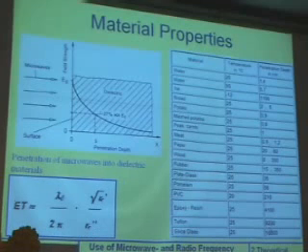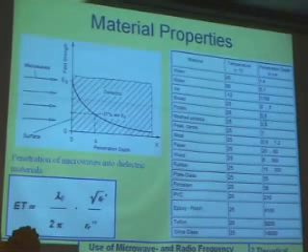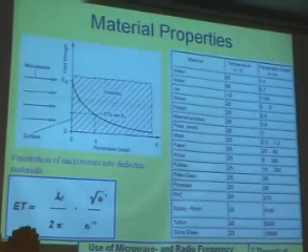If we change to, for example, Teflon, which is a very proven material to use in a microwave oven because it does not absorb microwave energy, Teflon has very low epsilon R, and therefore we have a high penetration depth. And if you look in agricultural material, for example, bread, you have 2 to 5 centimeters penetration depth with microwaves. Potatoes only nearly 1 centimeter. Mashed potatoes, perhaps 80 millimeters or something like this. Peas, carrots, 1 centimeter. Meat, about 1 centimeter. Paper, 20 to 60 centimeters. Wood, up to 350 centimeters, and so on.